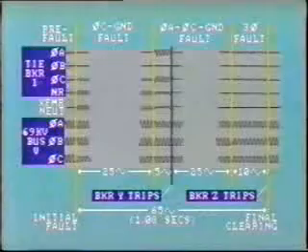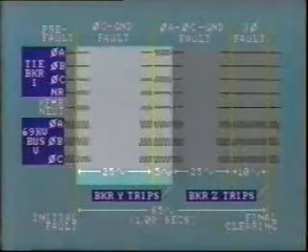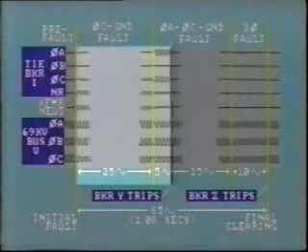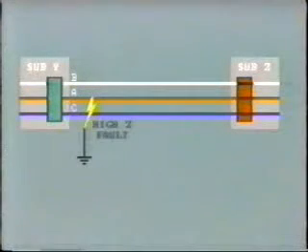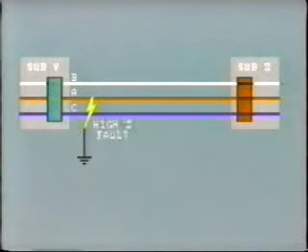At this point, breaker Y finally trips to clear one end of the faulted line. The tripping occurs 30 cycles after the initial line-to-ground fault started. This is reasonable since we are dealing with a high impedance fault. Thus, the level of fault current is low, resulting in a relatively long operating time.